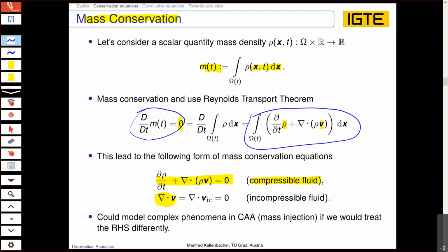It means that you can decompose each vector field into a vortical field, which will be for us the classical flow structures, because we have vorticities there, and into an irrotational field, and the solenoidal field, which can be described by the curl of a vector potential, the typical vortical structures, and the irrotational field can be described by a scalar potential, by the gradient of a scalar potential.